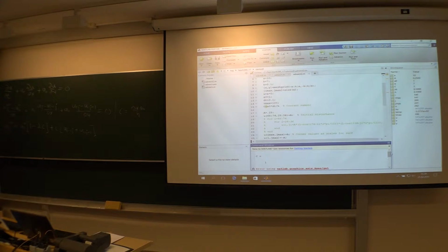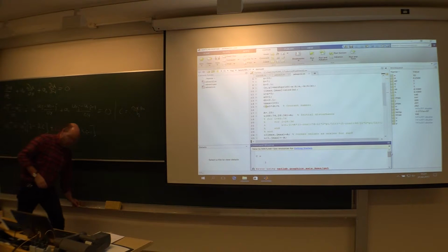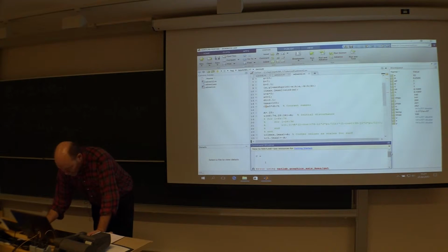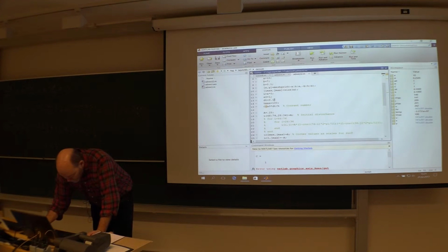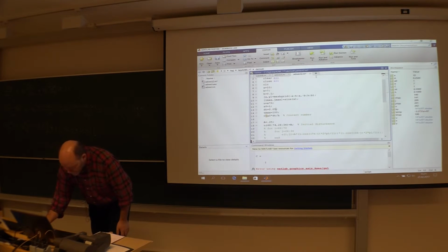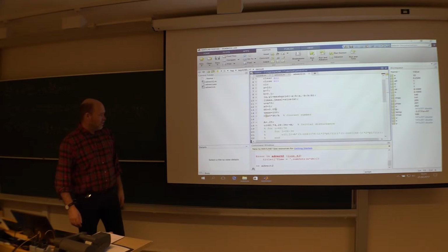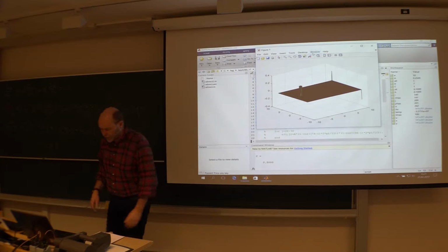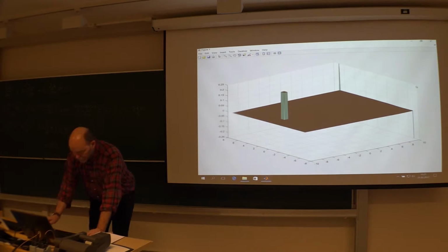Then the next demand: all coefficients positive. Then this will demand that your Courant number must be 1/2. Let's see if that is true. Courant number 1/2. Then I need a time step of, that was a little bit too much, 0.5 I think. Let's see if that's correct. Yeah, now I have a Courant number of 0.5. I should be just on the limit. Let's see if that one is stable.